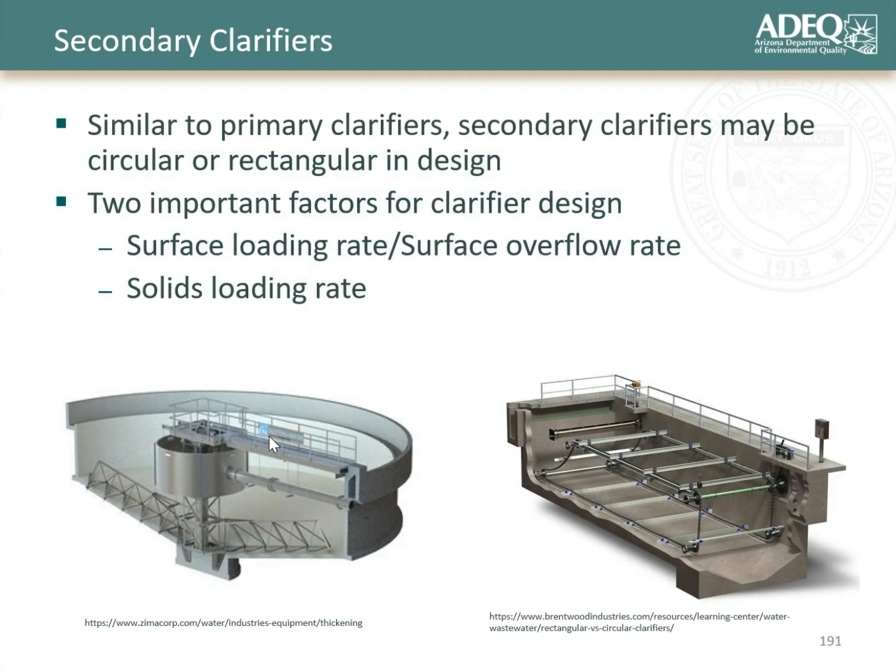Similar to primary clarifiers, secondary clarifiers can be circular or rectangular. The majority of the ones I've seen in the field are circular, but I have seen a few rectangular ones as well. It really is based upon your site plan and site development and preferences and a whole bunch of other considerations. But the two important factors for a clarifier design, no matter which configuration we're talking about, are surface loading rate or surface overflow rate and solids loading rate.